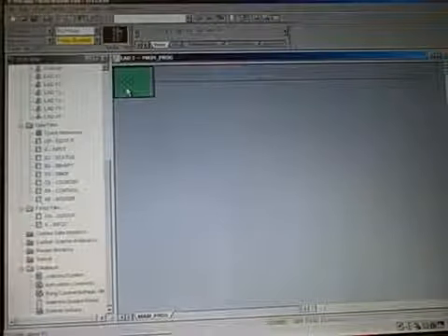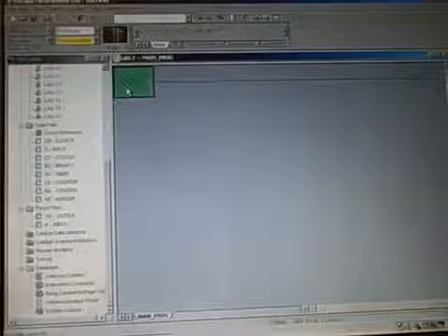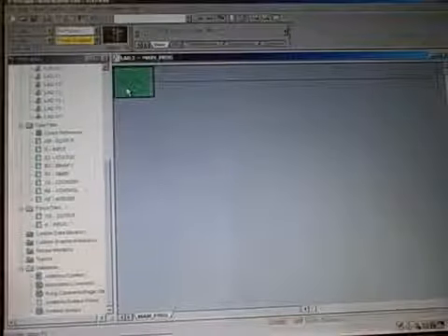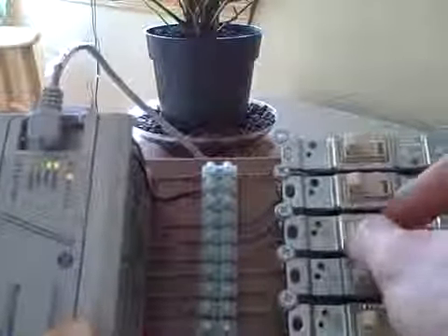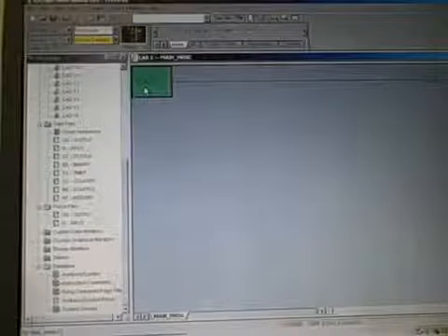I'm going to show you now how we can implement simple logical functions such as AND and OR gate type functions using contact and coil ladder logic programming in a small PLC. I have, in this example, a Micrologix 1000 Allen Bradley PLC with input switches connected so I can simulate different input conditions and I can watch the output statuses with the LEDs over here. Connected to this, I have my laptop computer running Micrologix RS Logix Micro Starter Lite software.